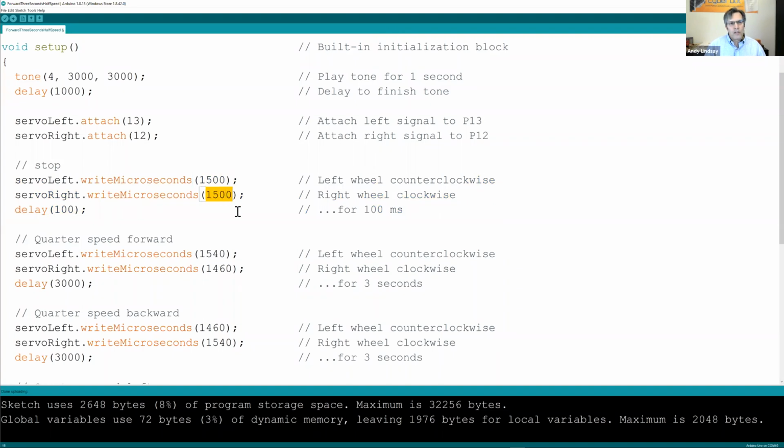And so the radio receiver on the airplane basically would take those radio bursts and convert them to high-low signals that it sent to the servo. And then the servo was designed to say, okay, well, I'm at 1500. That's basically 90 degrees for me. I'm going to turn to and hold the 90-degree position.